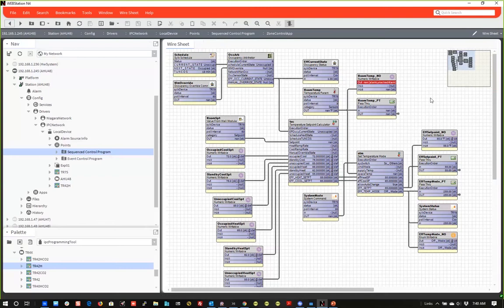And again, remember, it's Fox. Typically, it should be Fox Secure, Fox S. But you're going between controllers. Say, if a bunch of these are VAV versus an air handler, you're doing that communication by secure means with Fox and sharing data that way, so you're not doing a BACnet share or anything like that. You could just do a BACnet export to share it to maybe another BACnet IP device, if need be.